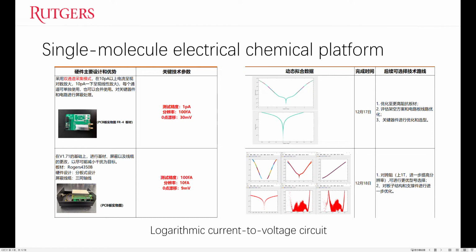We are measuring the linear output and the logarithmic output of voltage. In the previous version, I designed a PCB like the one in the first column. We can see there are two circuits on one PCB. The first one is the linear output, and the second one is the logarithmic output. Then I found there was huge noise between these two outputs, because when we measure such a low voltage, the noise can be a very big problem.